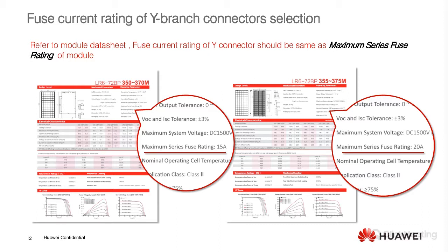In terms of selecting the correct fuse rating, we need to refer back to the module datasheet. So here is just an example of extracting that. On the left-hand side, you can see that the maximum series fuse rating is 15 amperes. And on the right-hand side, the maximum series fuse rating is 20 amperes. So this information needs to be selected from your PV module datasheet, and then the correct fuse rating can be incorporated inside of the Y connector, if that was to be a choice.